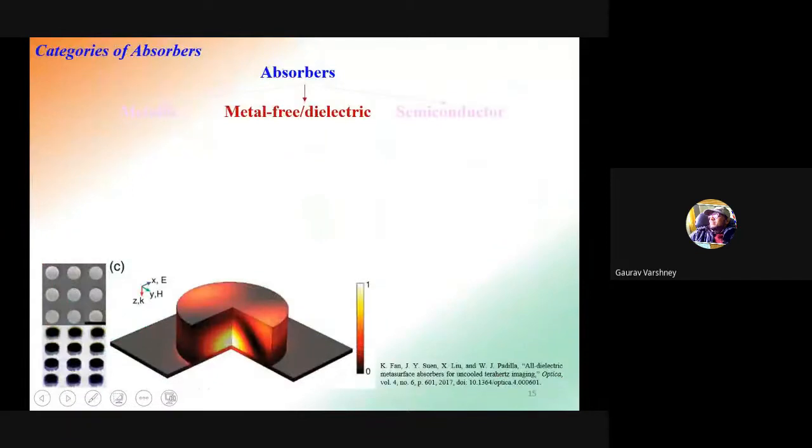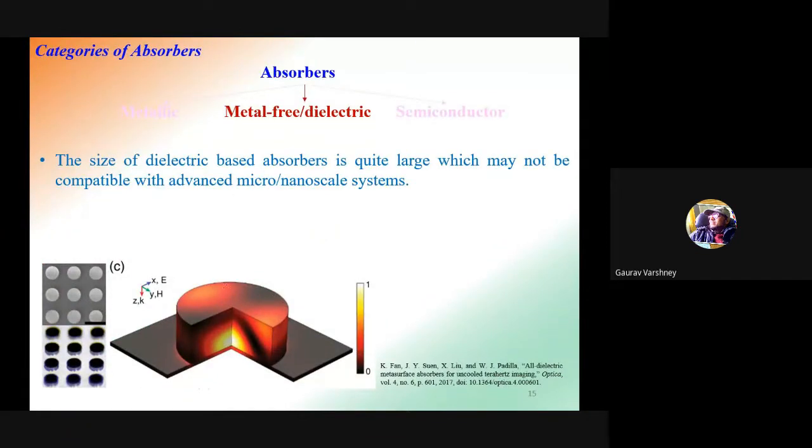And this is another kind of geometry. You can see over here, this is some dielectric made of TiO2, titanium oxide, dielectric kind of structure, silicon or gallium arsenide as well, and some thin dielectric spacer at the bottom. So if we take high thickness of this dielectric material with high permittivity, then what will happen? No metallic reflector plane is required, and total transmission will be blocked, and reflection is completely blocked because this unit will be utilized as a self-resonating structure as well.